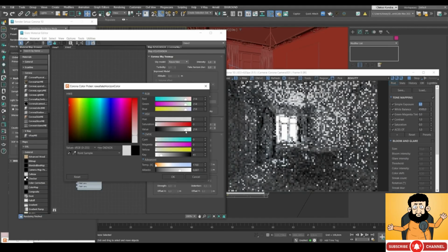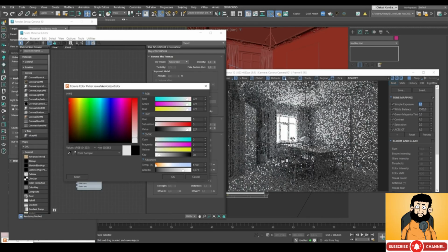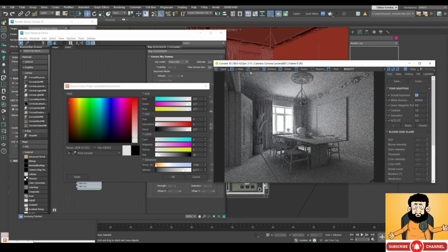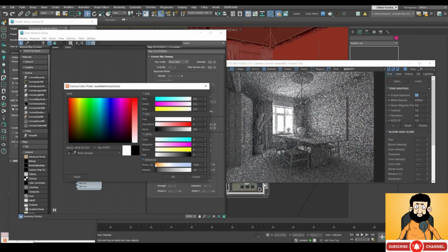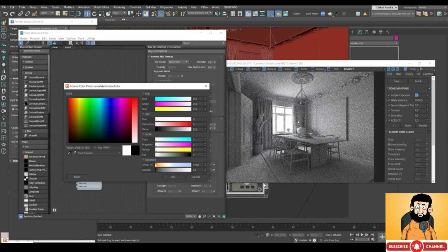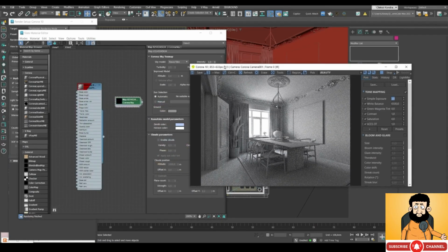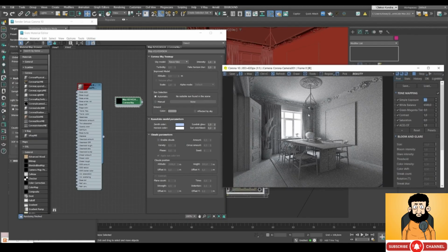So we can put either gray or purple white. That depends on the structure of the room. If the room is kind of elongated and deep, then we need to put a higher value so that more light comes through the window. So let's do it like this, for example. Now both the top and the middle of the horizon slightly interrupt the zenith, making it a little less blue.